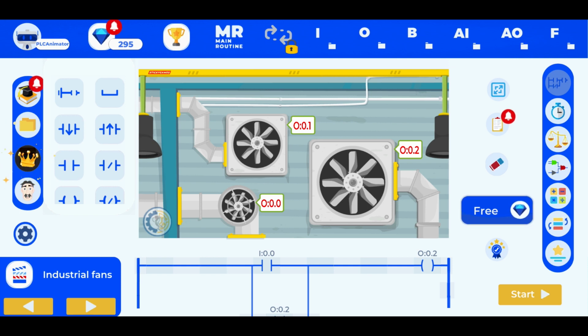So with this, I'm indicating to my PLC, my virtual PLC or physical PLC, that while my coil stays on, if it detects that it's on, then keep it energized. So first we send a pulse. It's going to power on for a few thousandths of a second, for a very short time. But here I'm detecting this. It's noticing this. So as an input, I'm simply playing with my memory.